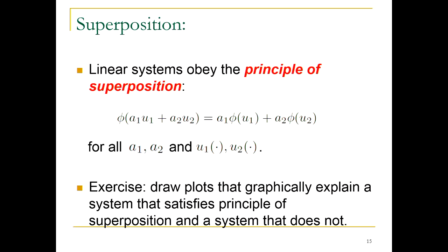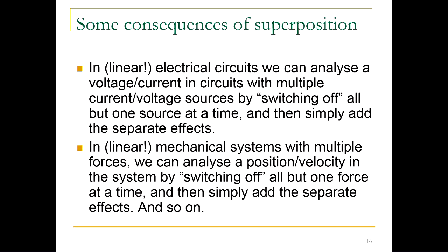All right, so you can draw plots to graphically represent, in a similar way that I was doing before, the superposition principle for yourself. Where did you see this? Well, if you are an electrical engineer or you did electrical circuits in some of your subjects, you may remember that if you want to calculate, let's say, the current through a resistor in a circuit that has multiple voltage or current sources, what you can do is turn off all sources but one.